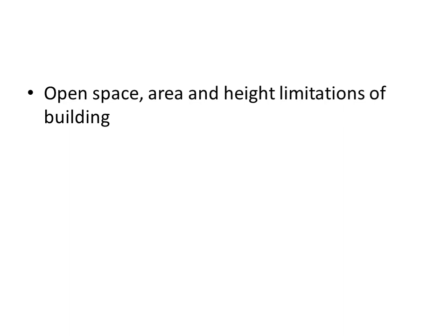Then following are the exemptions to open spaces. Projection into open space. Every open space provided, either interior or exterior, shall be kept free from erection thereon and shall be open to the sky, and no cornice, chajja, roof or weather shade more than 0.75 meter wide shall overhang or project over the said open space so as to reduce the width to less than minimum required.